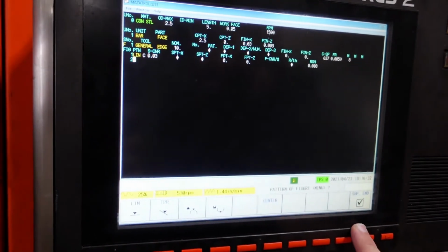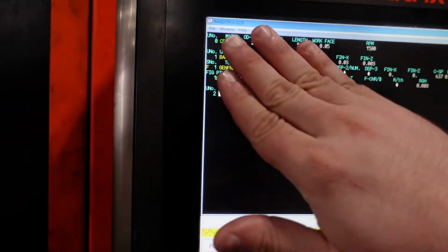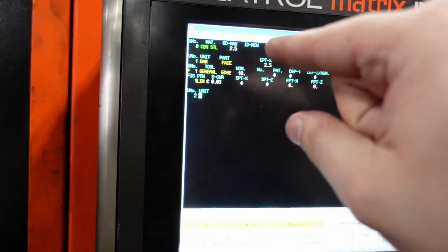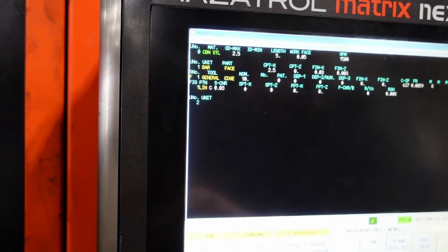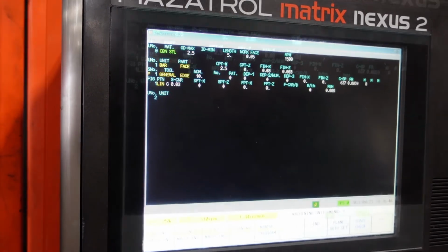So from this point, I'll hit shape end down here. This will end this. This is one block. This will come in, come down to 2.5, cut the chamfer, and face down to X0 in its Z0 position.